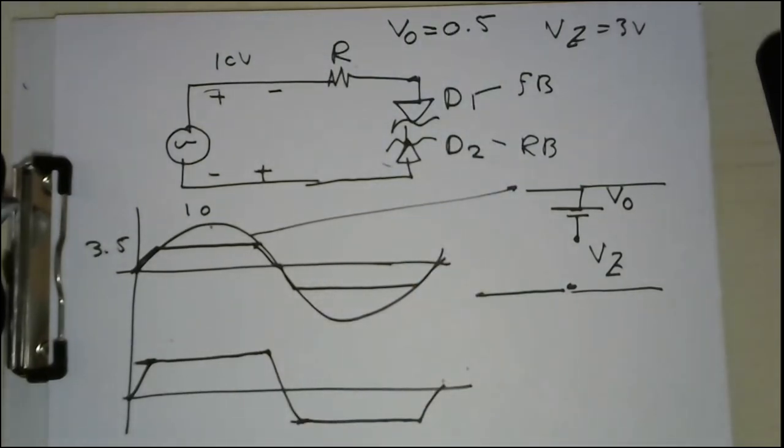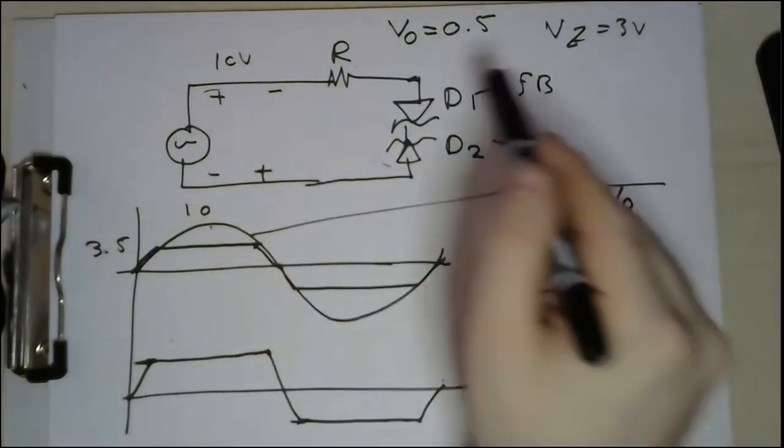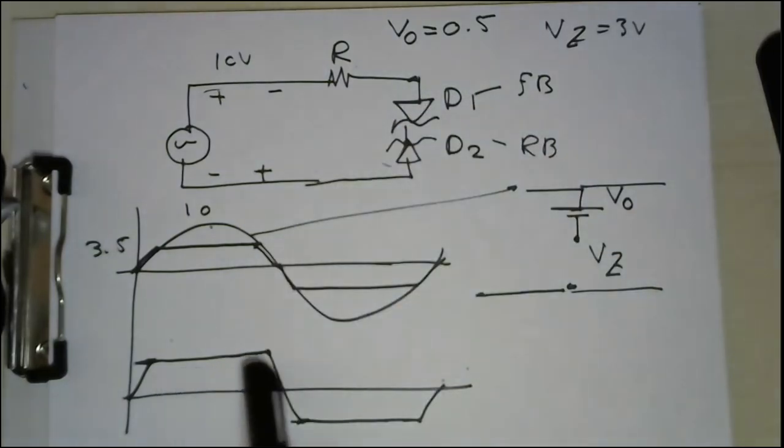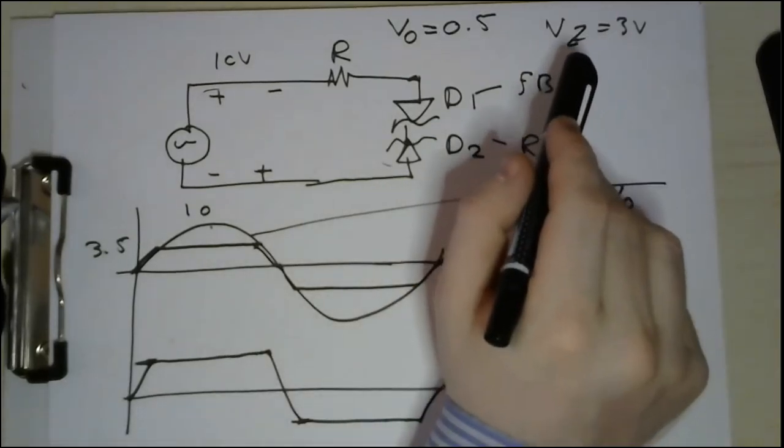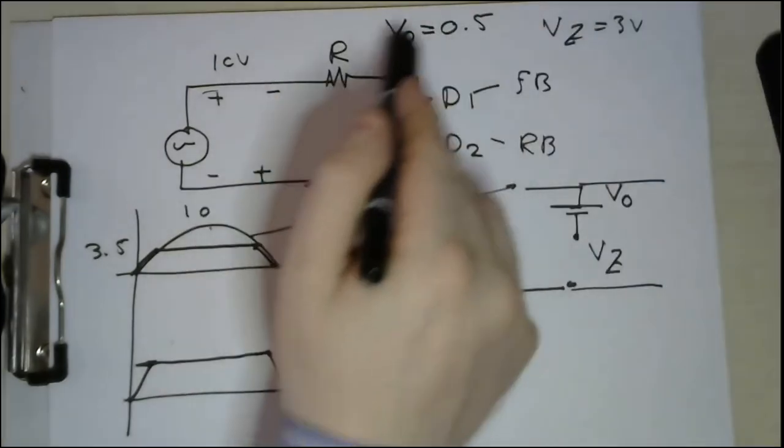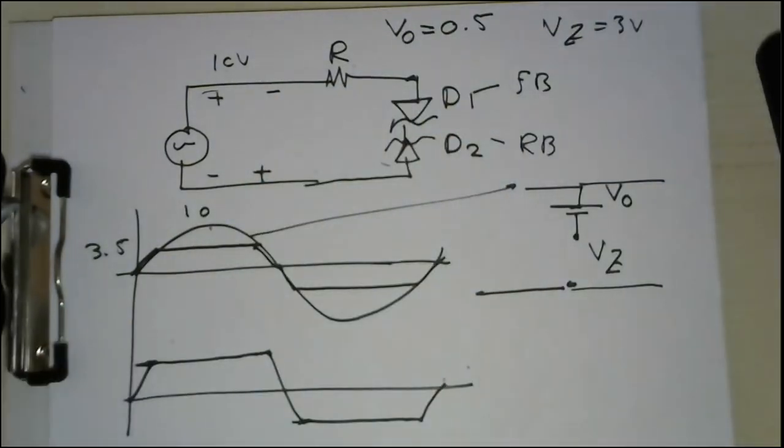If you recognize it well, it is some sort of voltage limiter in order to limit the input voltage to a certain stage. So you can limit the input of the next stage, which is the output of this stage, to any certain value based on your Zener configuration and based on your Zener diode. For example, you can use a VZ equal 3, 5, 7, 9, whatever the voltages, and then you can get different outputs. This is a very interesting application where Zener diodes play an important role.